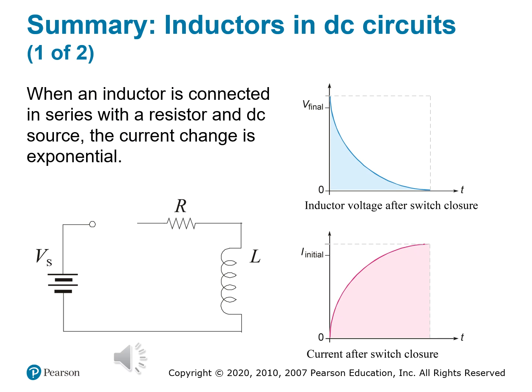And this behavior is defined by what's called the time constant. We designate time constant by the symbol tau. It looks like a fancy little t, or a fancy little capital T, however you want to describe it. It's the Greek letter tau, and it's calculated by inductance divided by resistance, where L is the inductance in henries and R is the resistance in ohms. And then that little fancy T, tau, is the time it takes the current to reach about 63% of its final value.